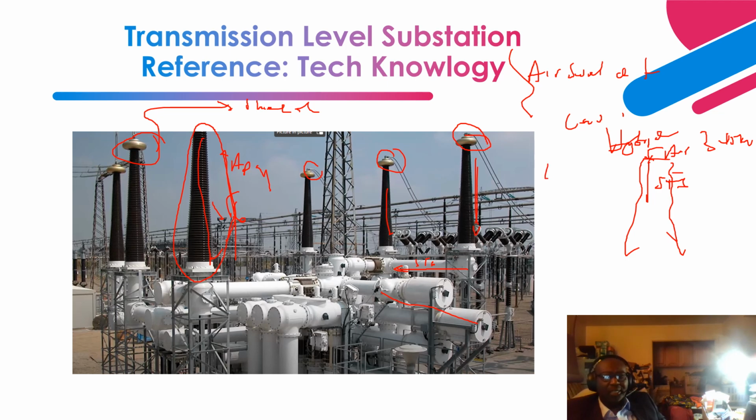And what is electric field? It's voltage over distance. As you can see over here, the connection point is very small. So if you have that 345 kV and a very small, minute connection point, the electric field is going to be very high in air, and it's going to break down the insulation around here and destroy this porcelain insulator. So we utilize a grading ring,